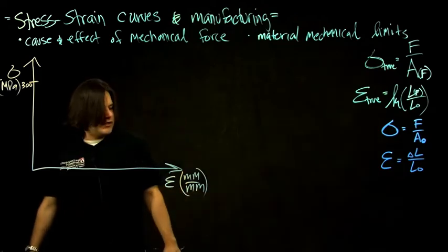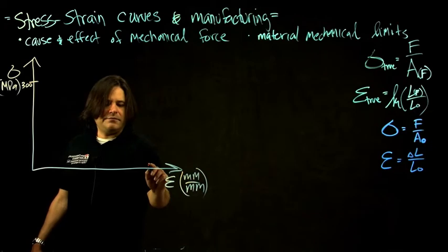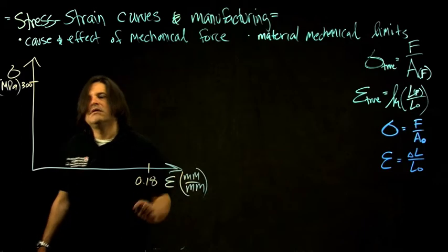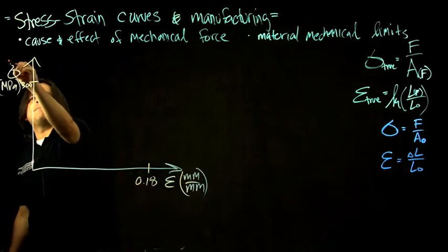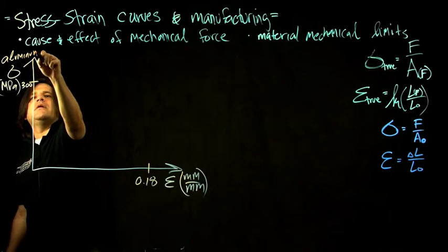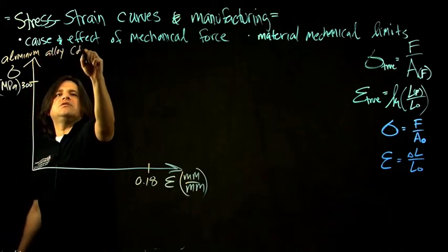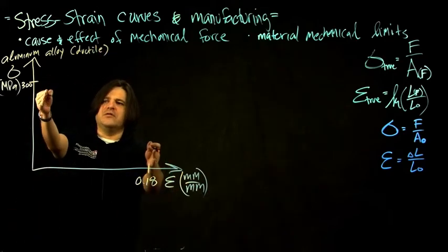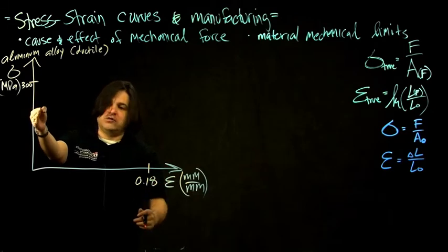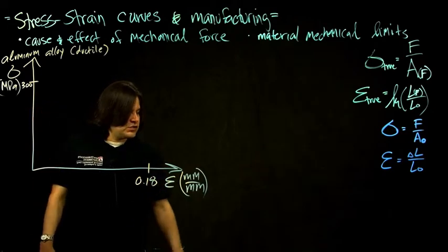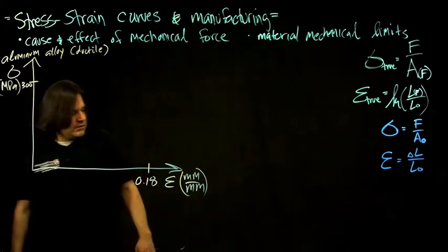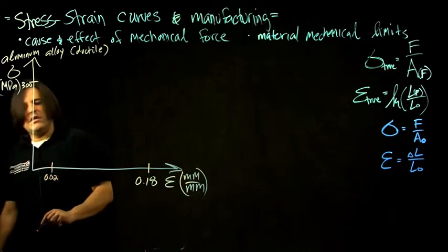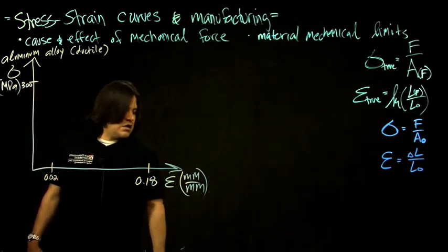So I'm putting this value of 300, and let's say over here, 0.18. So this would be like for an aluminum alloy, which is a ductile metal. This is the typical magnitude. From 300 megapascals of normal stress, you would have this amount of strain induced. And if we were to have this first notch here of 0.02 in the strain, millimeters per millimeter,